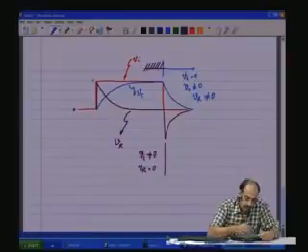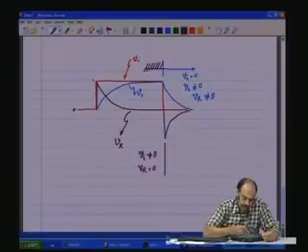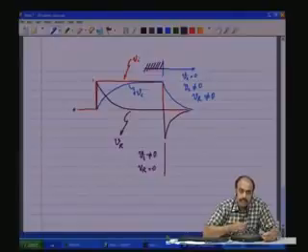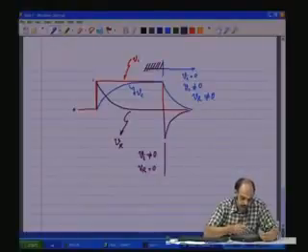So, the Vc transfer function does not have any 0, whereas in the case of Vr, it goes to 0 during some of this duration, and therefore there is a 0 gain possibility, which implies the occurrence of a 0 in the circuit and which reflects as a 0 in the pole 0 plane, which in this case occurs at S is equal to 0.